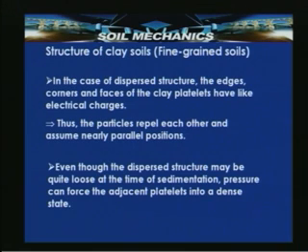In the case of a dispersed structure, the edges, corners and faces of the clay particles have like electrical charges. So, the particles repel each other and assume nearly parallel positions. A parallel arrangement, with face to face repulsion, will be there in the dispersed structure.